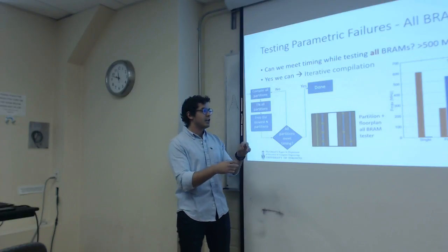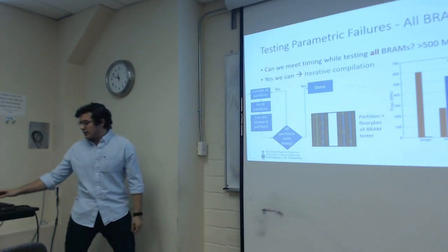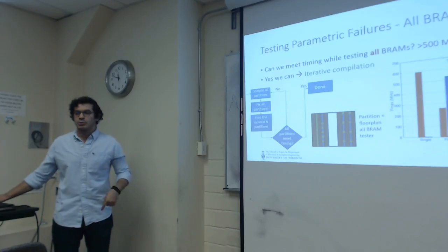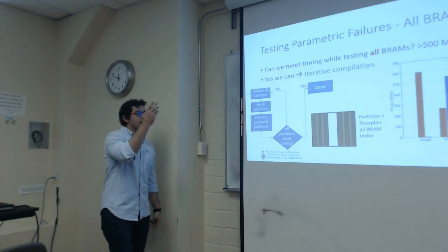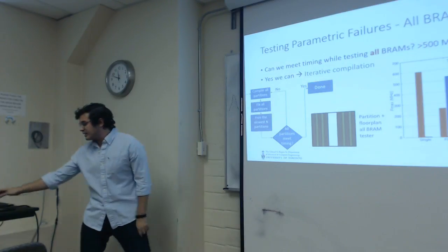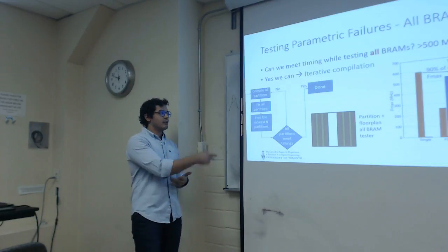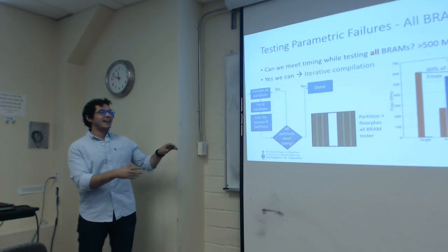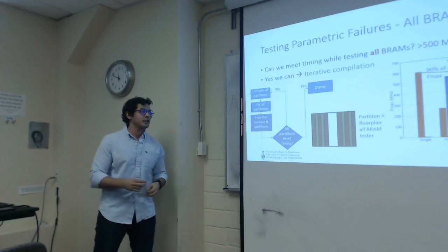So in this compilation, Quartus is only compiling a subset of these testers. And interestingly, with every compilation that we do, we notice that some more testers are meeting timing. After a couple of iterations, we're able to meet timing for all our testers, and we've managed to get almost 90% of the Fmax for a single tester. We did that for our testers, but we think that this is applicable for any other regular design.